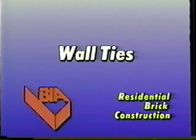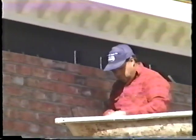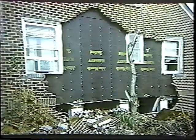Wall ties. Wall ties are essential structural elements which attach brick to its backing. Ties transfer wind and earthquake forces on the veneer to the backing. When ties are not installed properly, the brick wall can fall away from the house. It can also cause cracking to occur in the brick wall.